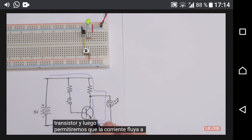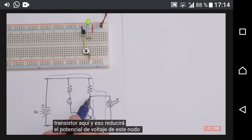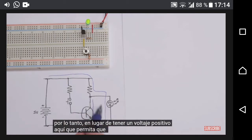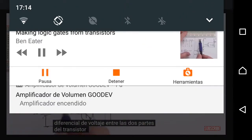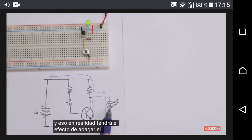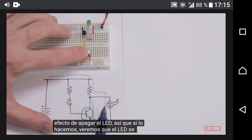The LED is on right now, but if we turn the transistor on, then we'll allow current to flow through the transistor here, and that'll lower the voltage potential at this node. So instead of having a positive voltage here that allows current to flow through the LED, we won't have a voltage differential between the two parts when the transistor is on. And so that'll have the effect of turning the LED off. So if we do that, we see the LED turns off.